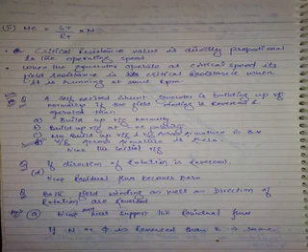The conductors will cut the residual flux, and current comes into the picture. When the current enters the field winding, it should not erase the residual flux, which means the field and armature should be properly connected. Then only the build-up starts. After that, critical resistance, critical speed, everything. So first preference should be given to residual flux. Second preference, field and armature properly connected.